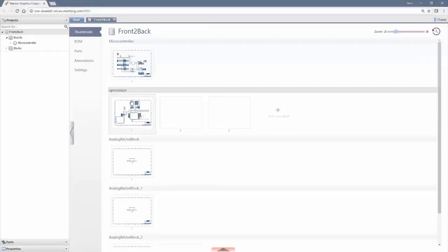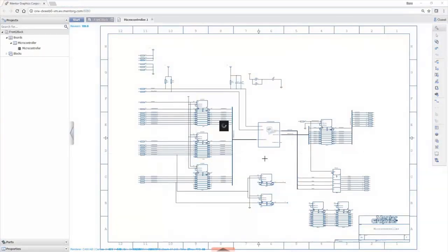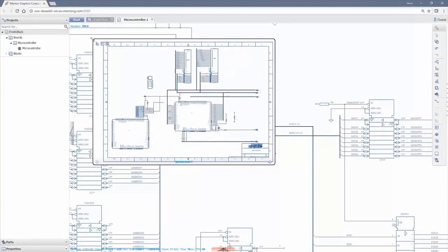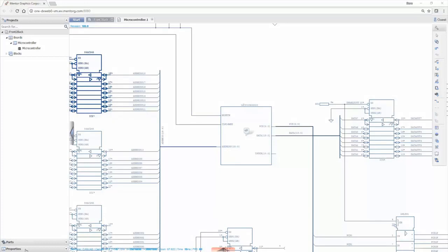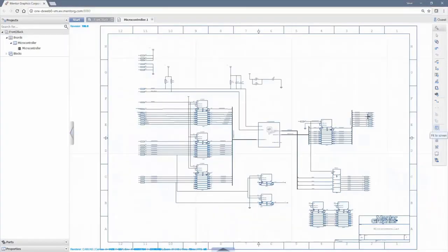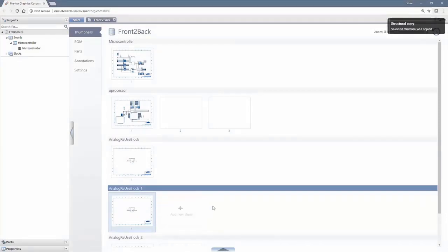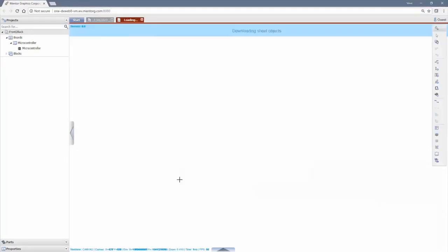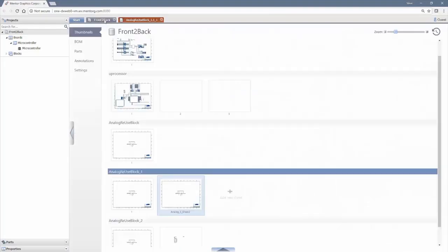A web browser-based Schematic Capture application gets you up and running quickly within the familiar native environment you use every day. Define the logical connectivity of the electronics, place the parts, connect them up, and edit the schematic to define the net names. Include properties such as manufacturer part number and reference designators for identification within PCB layout later and ensure correct BOM generation. Copy drawing sheets to easily replicate multi-channel designs.